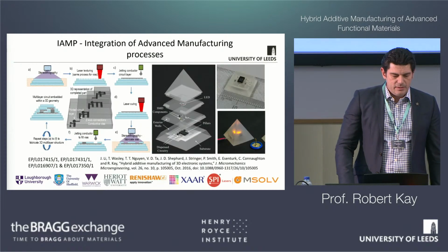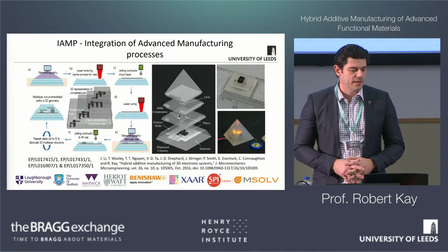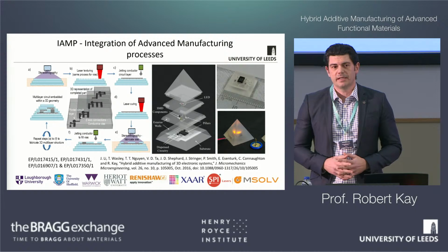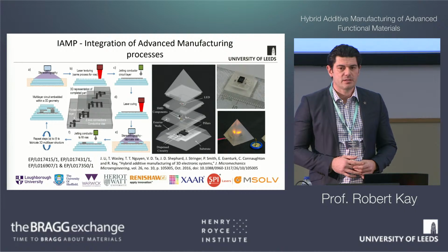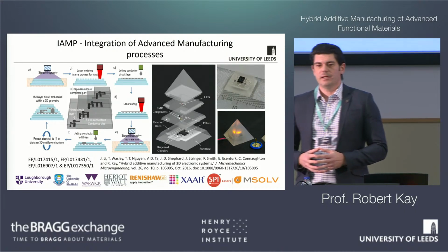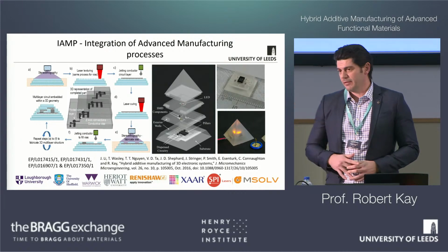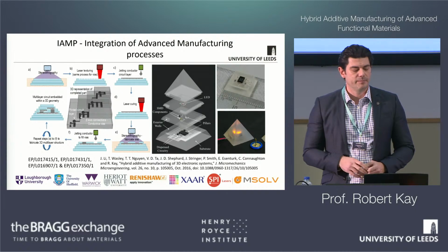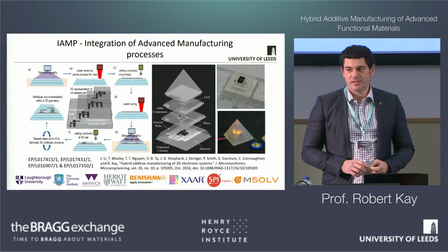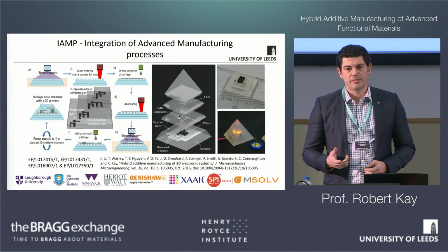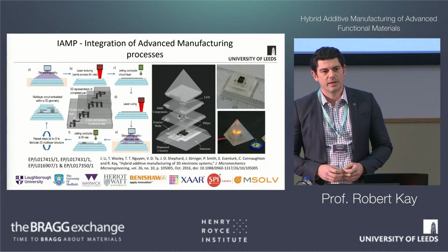I started out in earnest about 2013 on a project between 4 universities, and we were trying to use existing 3D printing techniques. We used things like stereolithography and dispensing of silver paste. And yes, we were able to make a 3D multi-layer electronic device, a very simple demonstrator, a 555 timer with a little flashing LED. But the problem was that we couldn't make anything high performance. They had a tendency to fail. If we dropped one off the bench, it instantly stopped working. So it wasn't going to be the future, in my opinion.